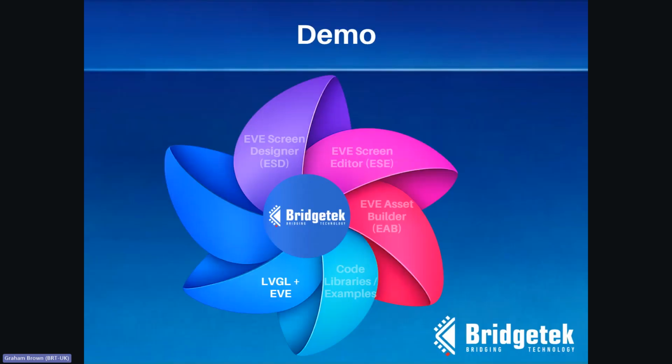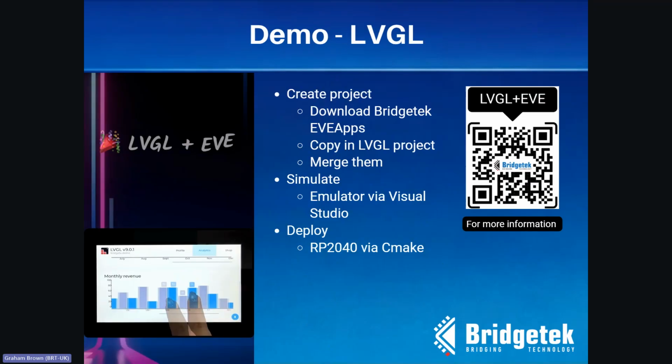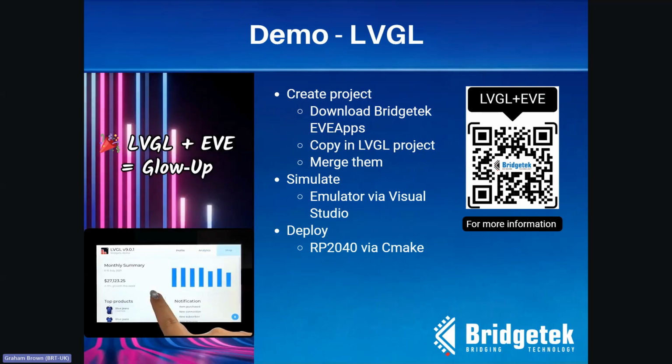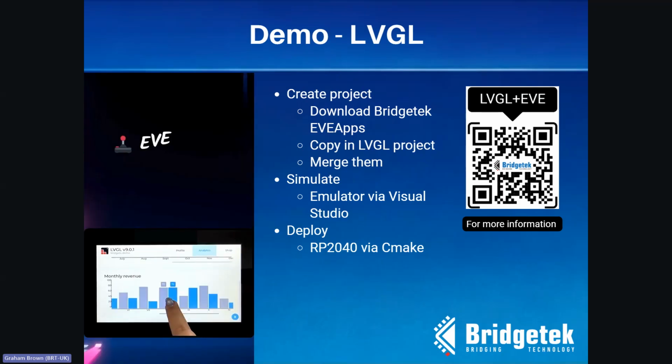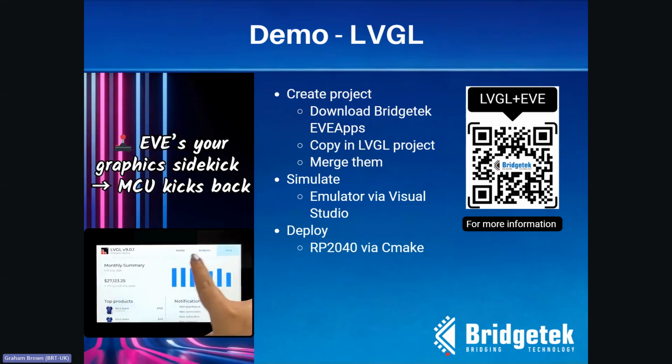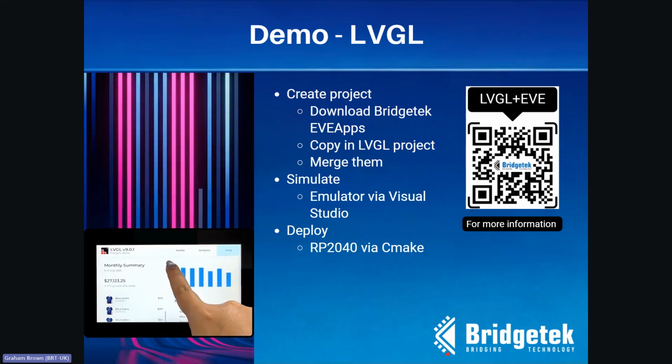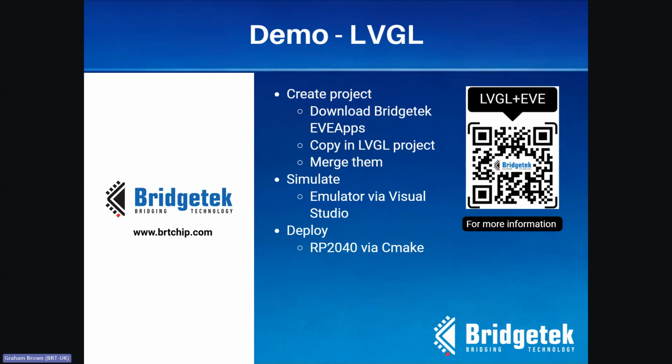The next platform we're going to talk about is LVGL, and how you can run your LVGL project on EVE. In this example, we're going to show you how to download the Bridgetek EVE Apps library and how to combine this with the LVGL project. We're then going to show you a simulation via the emulator on Visual Studio, and we're going to deploy it to an RP2040.